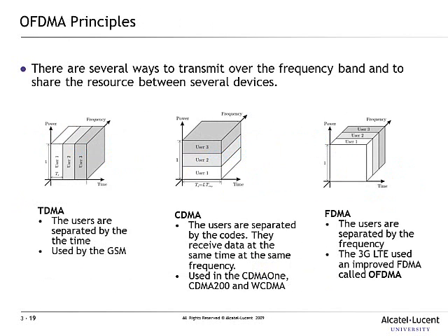Okay, just before we start going into OFDMA, just to recap, and most of you should know this, some of the first generation mobile communication systems were primarily FDMA based. So in FDMA, every user had a chunk of frequency band, and only that user was allowed to transmit. But the main problem with FDMA systems is that they don't make efficient use of spectrum.